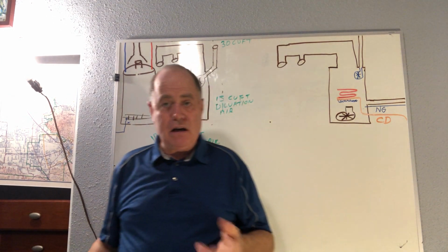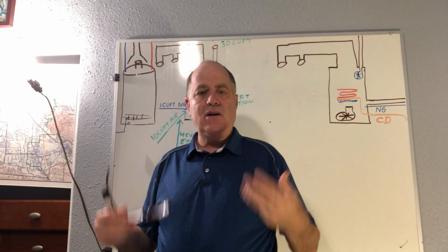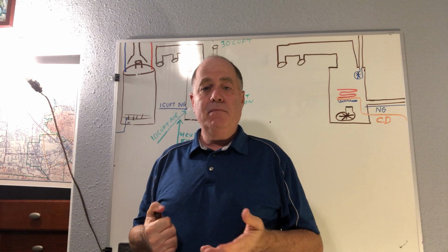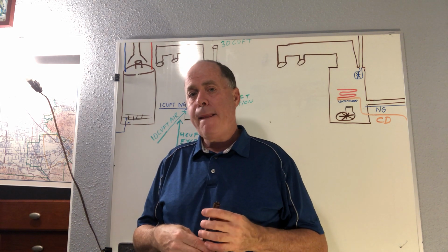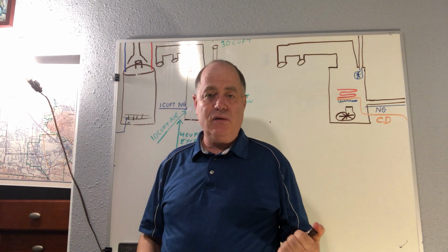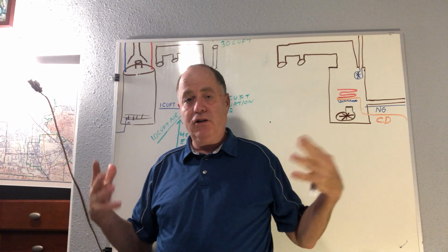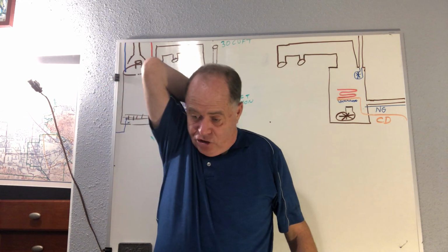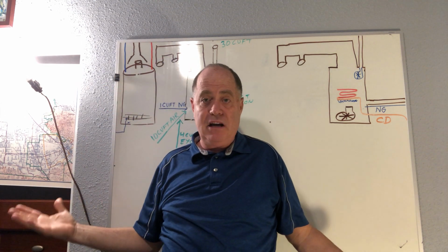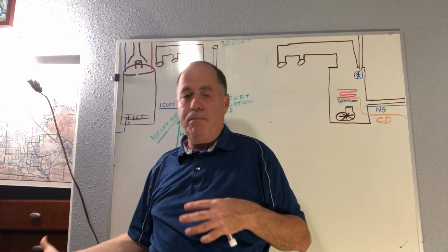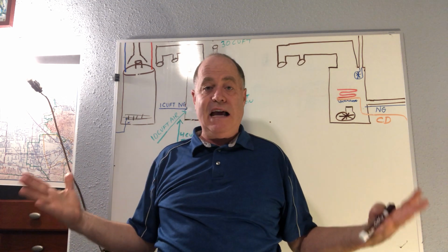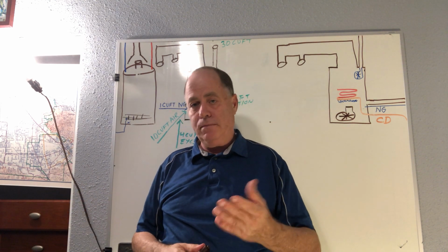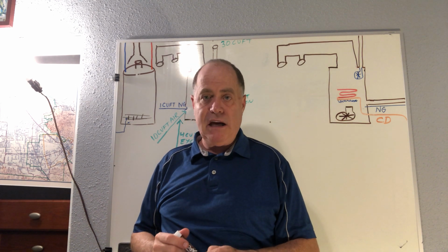Now, makeup air. What is makeup air? Let's say you have a furnace or a hot water heater, or even a dryer, that uses air for combustion that's in the house, or in a commercial building or whatever. If you don't have proper ventilation, windows that can open, or enough infiltration, you have to provide the makeup air, whether it's through natural means by opening a window or infiltration, or having an actual fan that's bringing air in so that you have enough air for your heating appliances, okay?